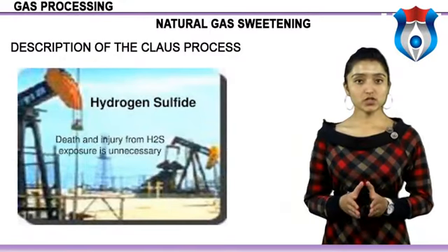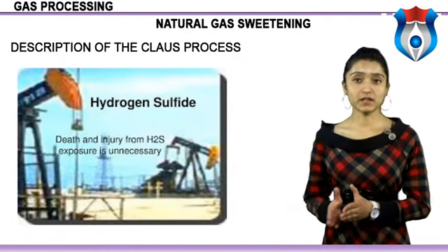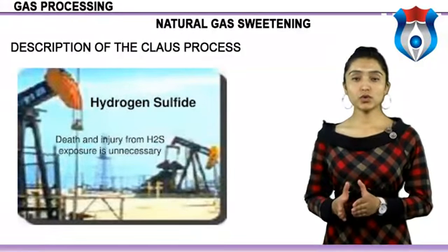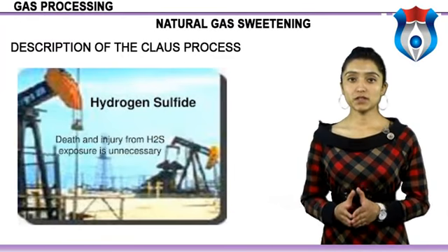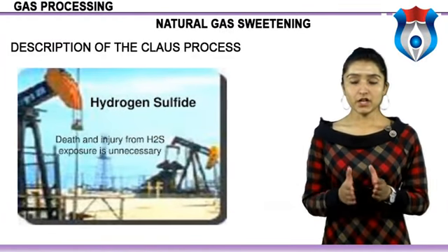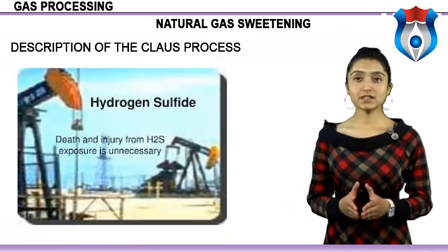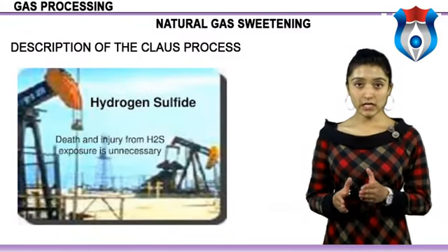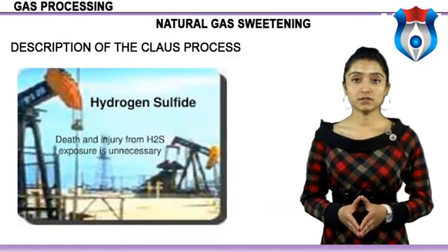Unfortunately, the reaction does not go to completion even with the best catalyst. For this reason, 2 or 3 stages are used, with sulfur being removed between the stages. Engineers know how different factors like concentration, contact time and reaction temperature influence the reaction, and these are said to give the best conversions.